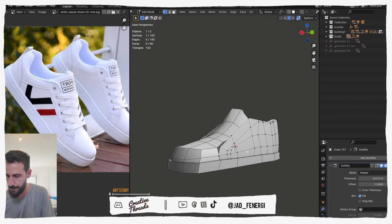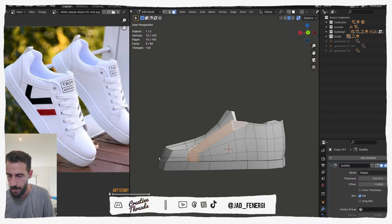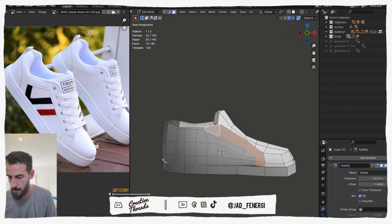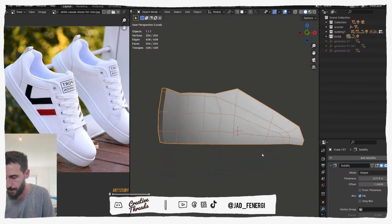So what we ended up with is this guy here that we need to add holes to. So we can either do this by Boolean or we can do it by geometry. I'm probably gonna do it with geometry instead of Booleans. So first let's fix the shape as much as we can.